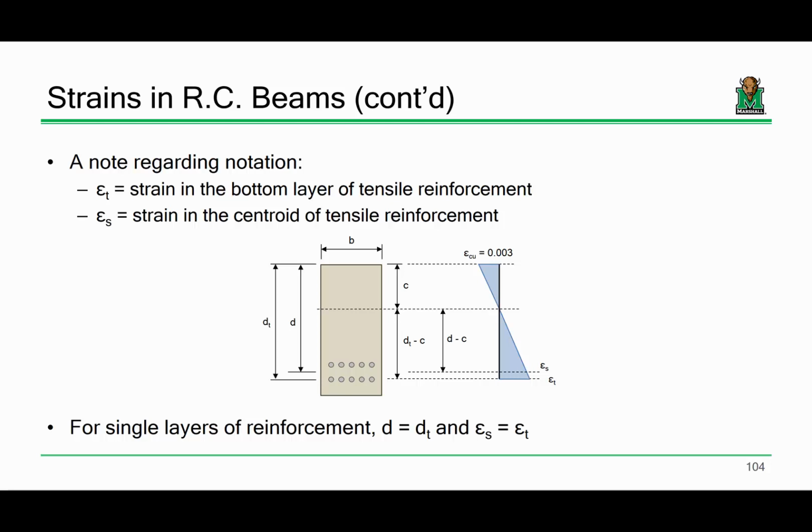They also apply vertical. What's that? They also apply vertical loads with the pre-stressing? Not really. Actually, it's usually just here's the beam, and you run the cable in the tensile region. That's usually what you do. Now, if you have a post-tension section, you can run the cables in a parabolic fashion that can sort of counteract the moment diagram. But I mean, we're getting into some areas. I can talk about this stuff all day. Any other questions?